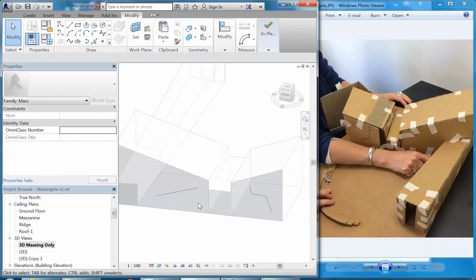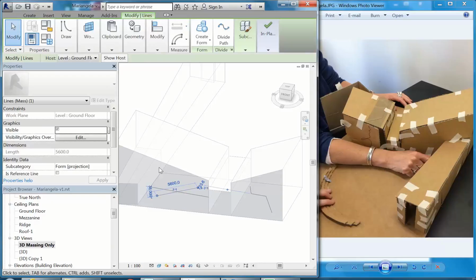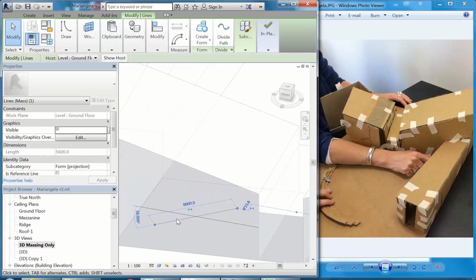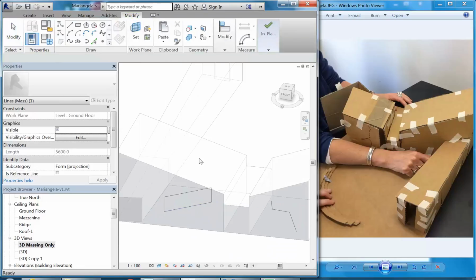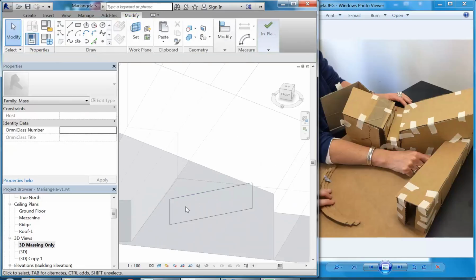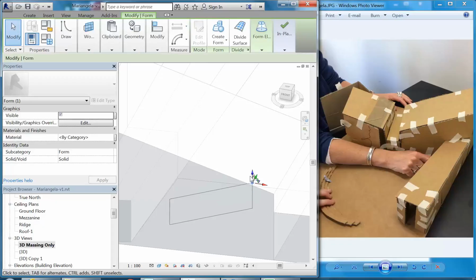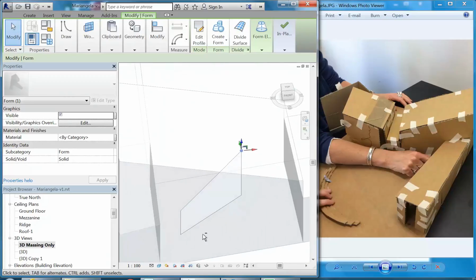So what you should be doing is extruding everything separately if you don't want one of those operations. And you can do a lot just starting with an extrusion. So again, by selecting that shape by itself and then Create Form, it'll give me what I'm expecting, which is an extrusion. And now I can select one of the corners and stretch that separately. I can also move it.